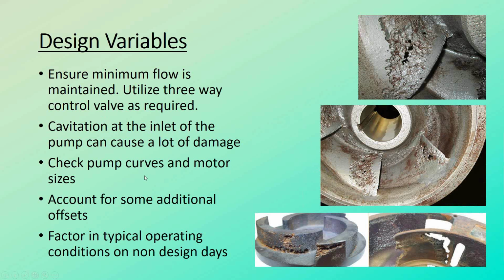So when you're designing your system, check your pump curves and motor sizes. Again, make sure you're not on the edge of a selection. Make sure you're not teetering on either end. Account for some additional offsets in your actual system itself, the way it's installed.